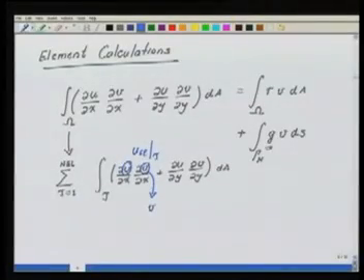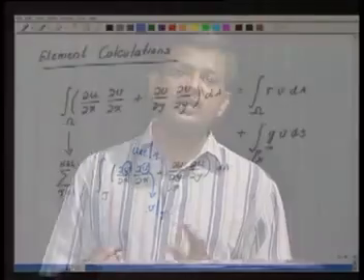Okay, so V would be again given as V over tau. Here we are talking of which global basis functions are going to be non-zero in this element. These are the global basis functions which correspond to the Ni tau, that is the shape functions of the element. So essentially, as far as the contribution of the element is concerned, the element is only going to contribute to the rows in the global stiffness matrix, or in the global equations, which correspond to the phi i's which are non-zero in the element.